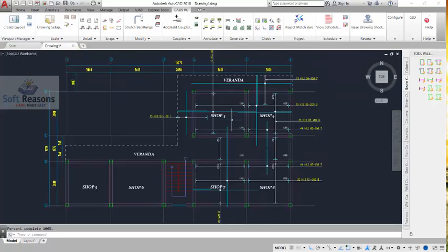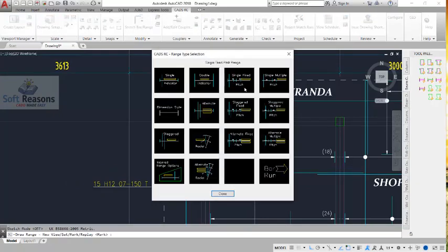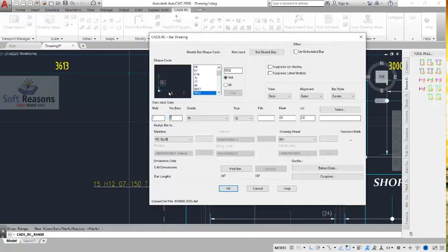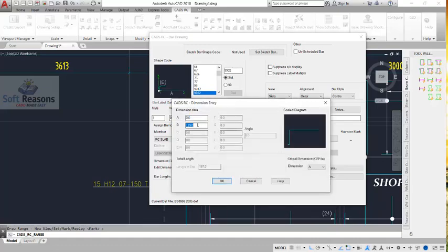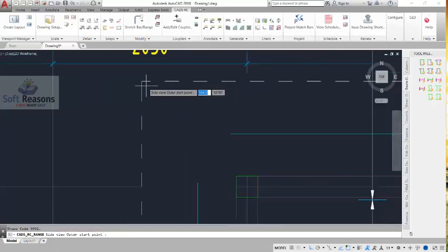So the same method used to detail here is the same method you are going to use here. So let me just complete something here. There should be a bar right here. Okay, so we get back to these provisions again. Pick this same bar shape we're going to be using. So we give it a name as a top bar, sorry, bottom bar right there. For the returns, we're taking it to be 2000 millimeters. Click on the OK options and then OK. So we pick this point.